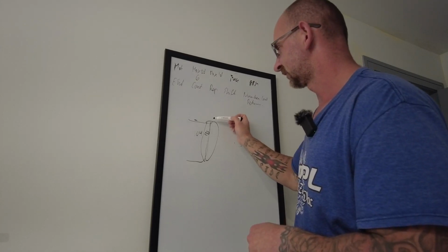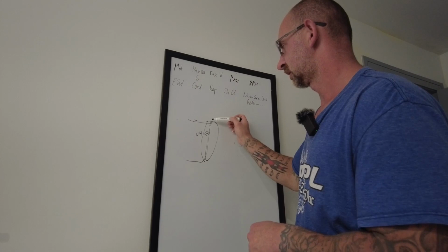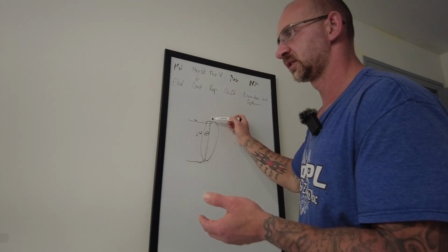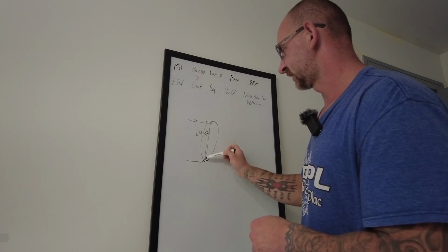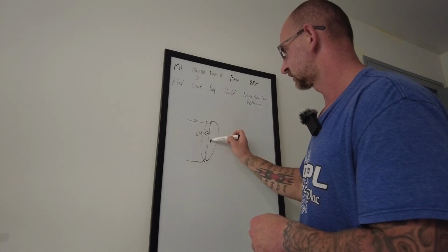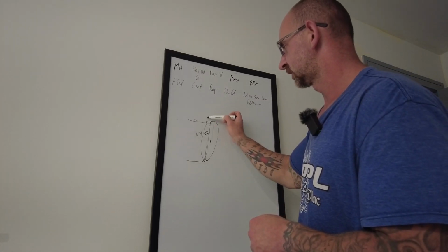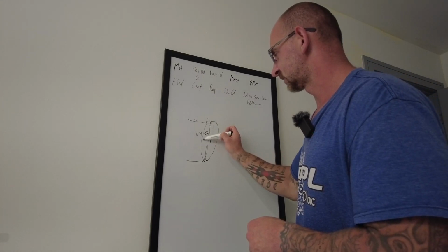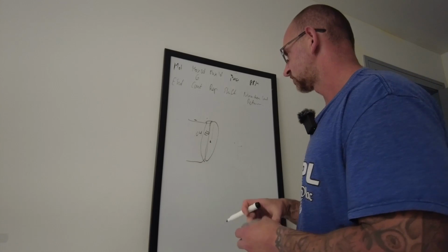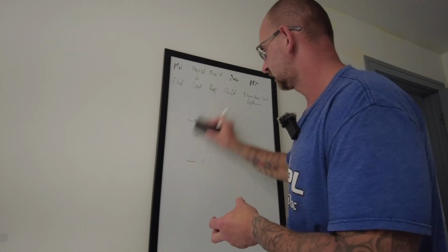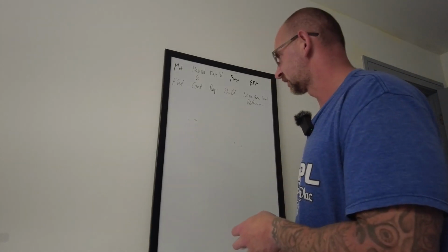Then she's coming down to 40,000. Let's say you're removing 20,000 on each pass, so it's gonna come down to like 20,000 plus. It's gonna face, right, to center, retract, come down. Then it's gonna come down to 3,000, retract, and then it's gonna go home. But imagine sometimes when you do a lot of shaft work, right?